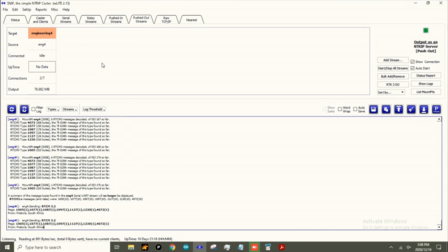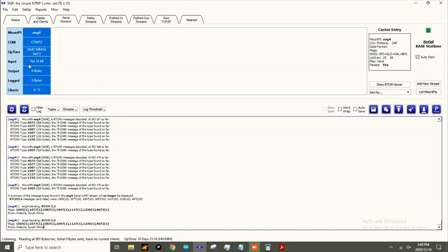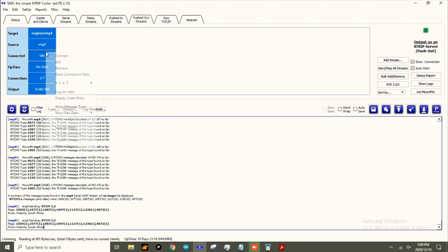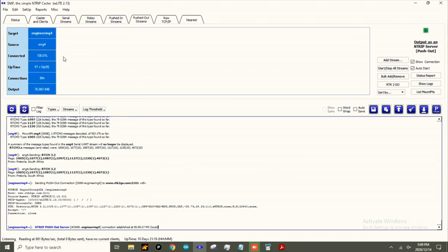If we go back into our SNIP utility, we have the serial input stream pushing in data. You can see it's not too much data, but it is actively coming in. And we will now activate our output stream, taking this data from the receiver, sending it to the server. So I'm going to click connect. And there you will see that the uptime is climbing very slowly in number of seconds, 8 seconds, 9 seconds. So it appears we are connected to RTK2Go, and you can see there's a few statistics down here sending that data through to the server.